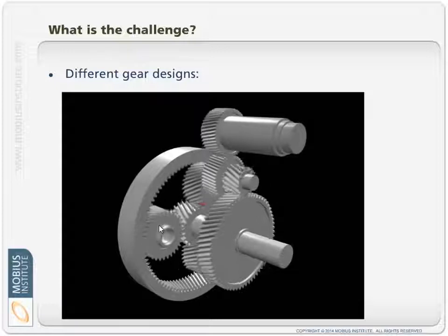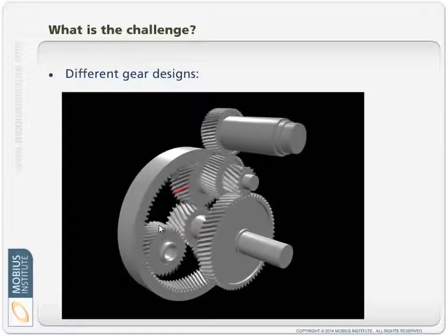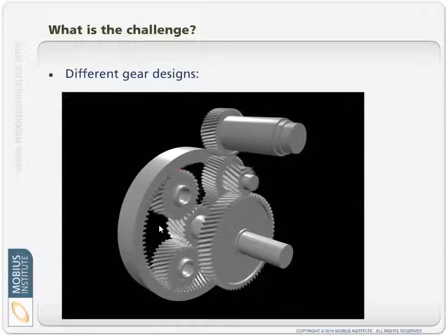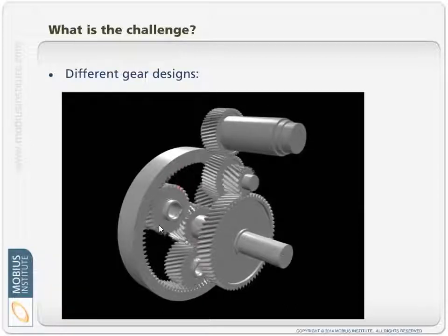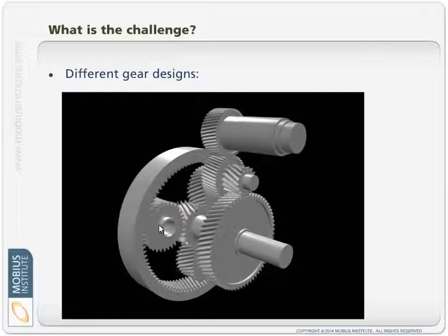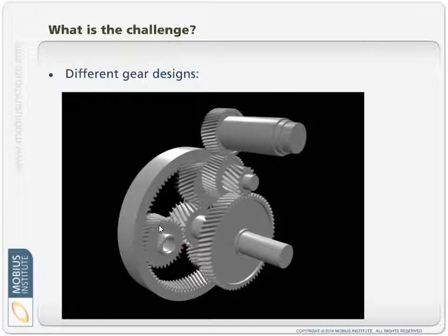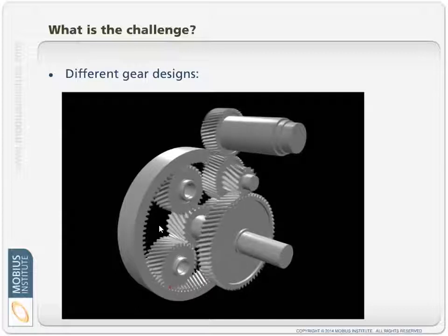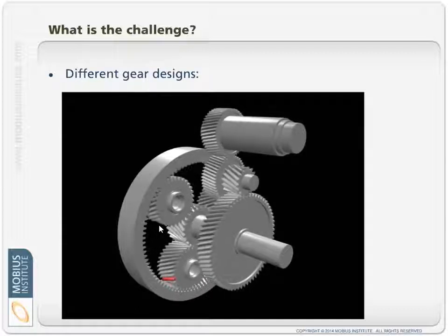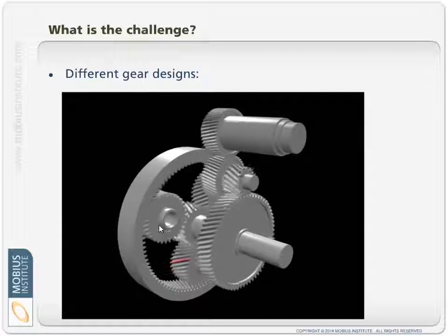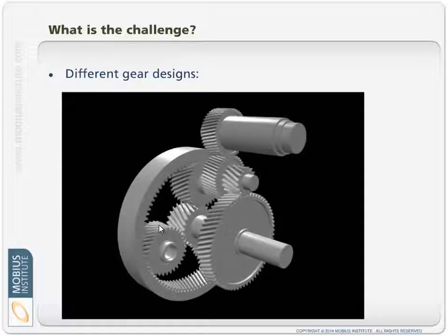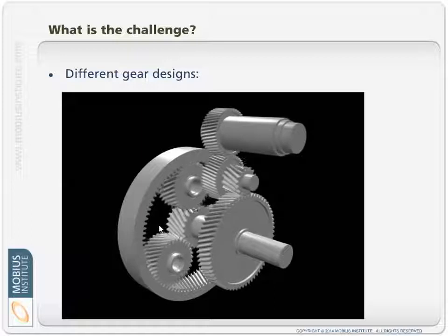You've got to think about the different failure modes, and that's certainly something that will help you with vibration analysis of your particular gearboxes, to consider what the failure modes have been in the past if you've got a long history with the machine. So at least you can make sure that you can detect those fault conditions. As with everything in vibration analysis, sometimes you have to make compromises.